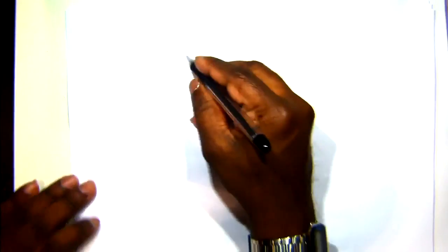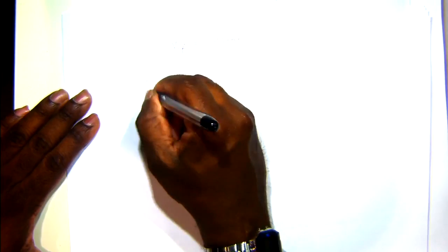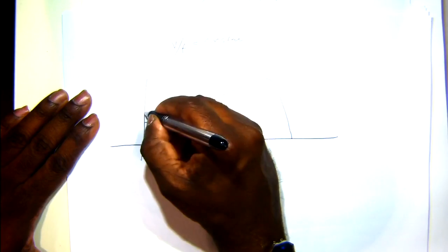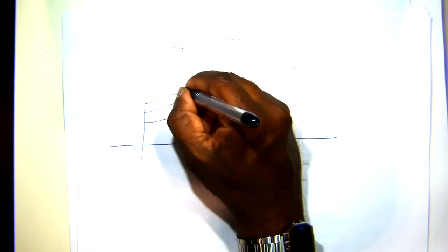So if you look at the torque speed characteristics when you're operating V over F control, constant, let's say I'll draw this one here and then something like this and then another frequency, let's say 3 frequencies. This is frequency 1, frequency 2, frequency 3.